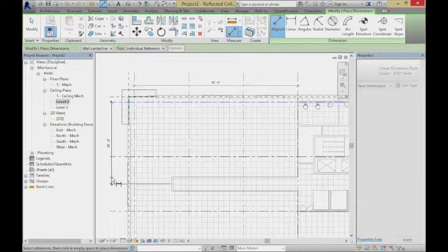Great. Okay, now let's go through and multiply that. Let's say we need a minimum of 4 air changes per hour, so multiply that by 4, and then divide that through by 60. So what I'm doing is the volume times the air changes, and I'm going to divide it through by 60, which is really just minutes per hour. Okay, so what does that come up to? 960.